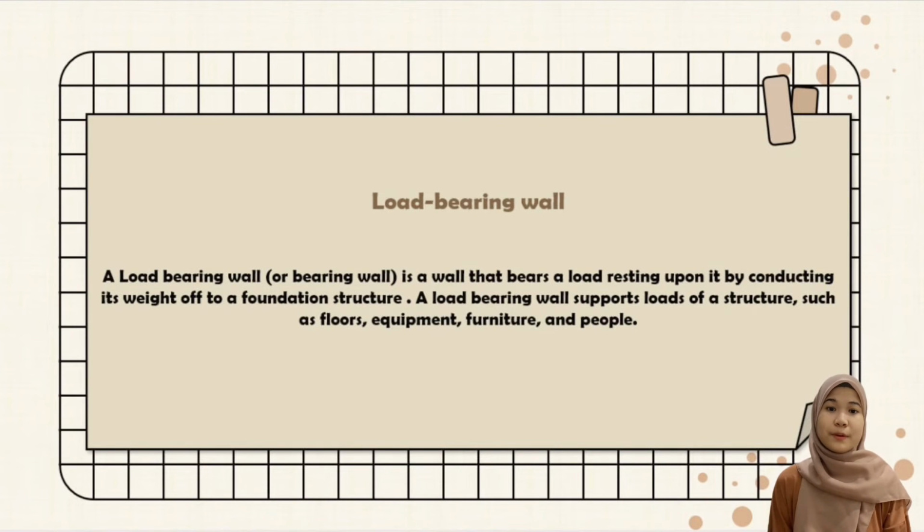Secondly, is load-bearing wall. A load-bearing wall or bearing wall is a wall that bears a load resting upon it by conducting its weight off to a foundation structure. A load-bearing wall supports load of a structure such as floor, equipment, furniture, and people.